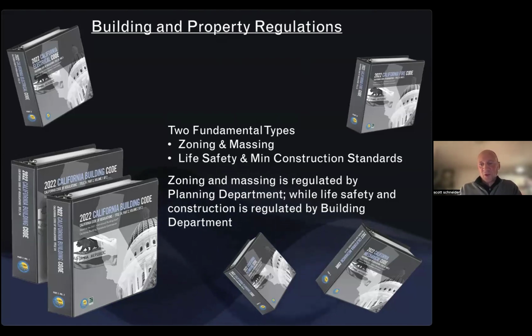An example of where things may overlap is if we look at allowable building areas. The planning department may have a rule that your building can only be a certain number of square feet. The building code also governs the overall square footage, but for other reasons. Usually one of the overlapping regulations will overrule the other.